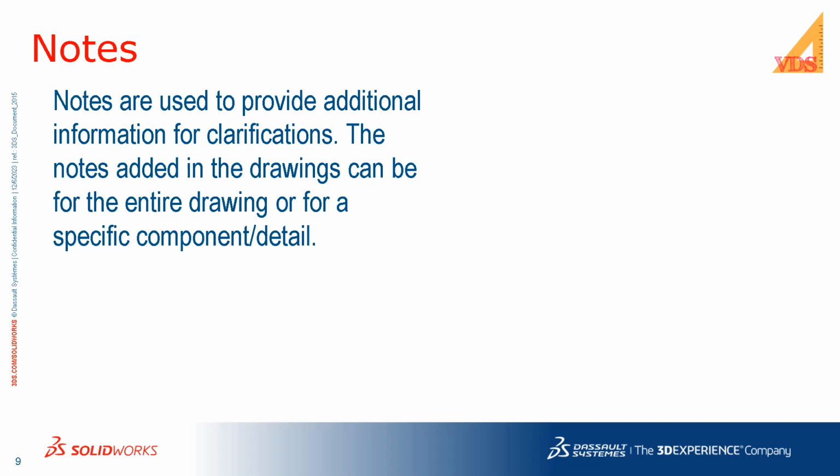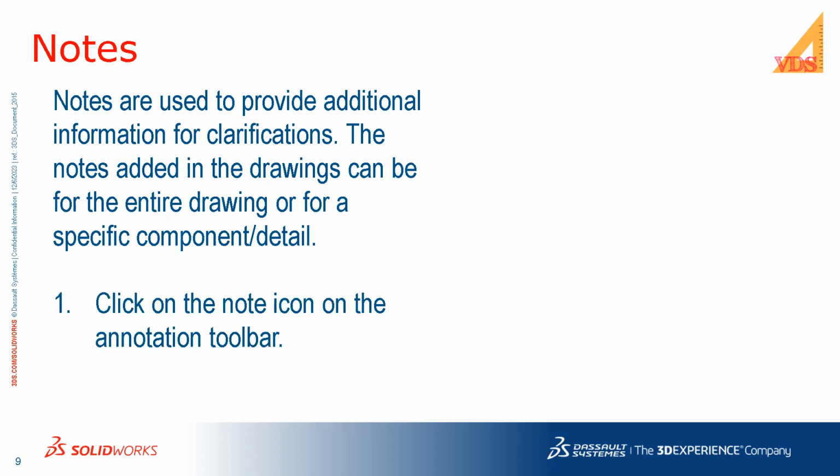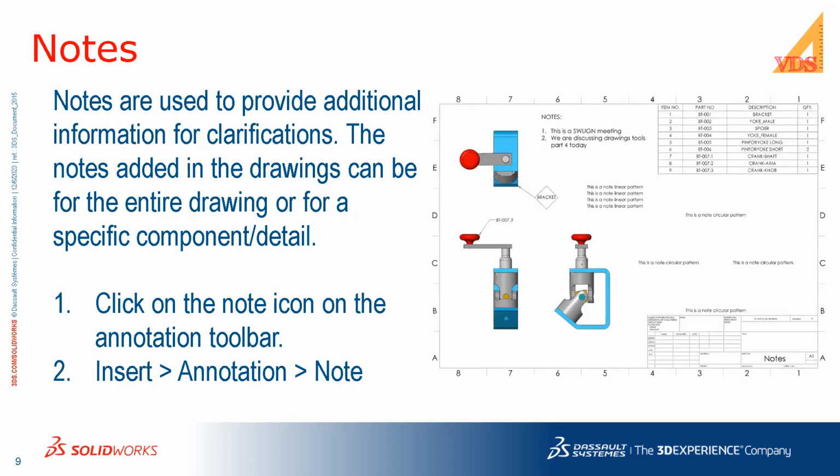thickness. So that way, the notes are helpful where we can use them to our needs and provide the required information to the person. We can also put the notes into our library, and instead of typing them every time you make a drawing, you can just drag and drop them from your library. We simply click on the note icon and just start writing like we type in a Word file. So we can click on the note icon, or we can have it from the annotation toolbar. Oh, sorry, the annotation menu.